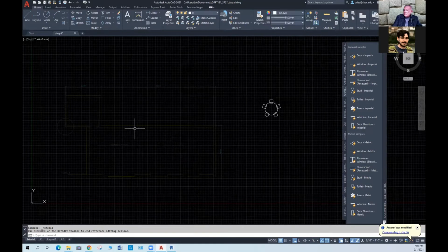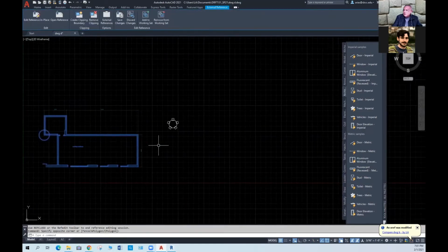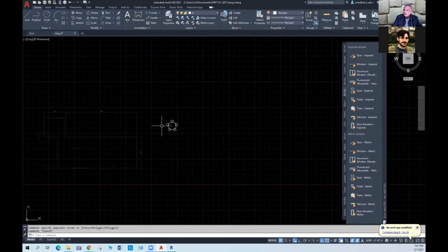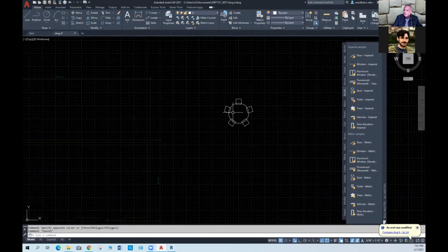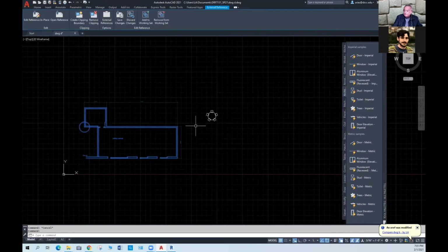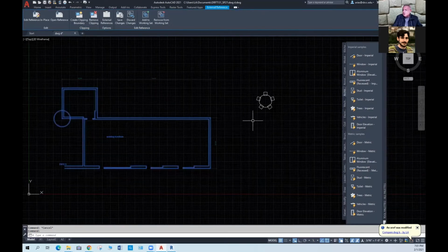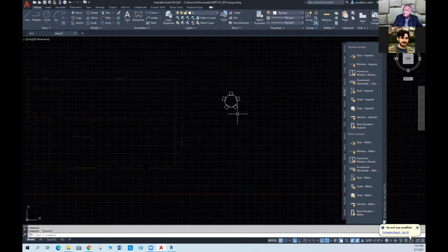And see, there's a drawing here. I can see the drawing there, and I can see the block. I don't see the other copies because I'm going to edit the reference. But I can see the drawing that I'm working on. And so it's important sometimes to edit the block with reference to the space that I'm in.